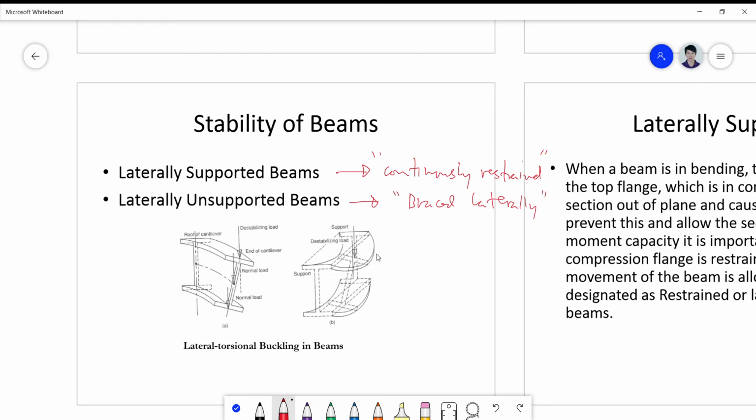Okay, so there may be a beam, maybe a secondary beam bracing, a lattice bracing coming from, or connected from, one beam element to the other beam element. Where do you connect it? Will you connect it at the flange, the bottom flange rather, or at the top flange, or at the web? Those are things that you need to look into also, no?